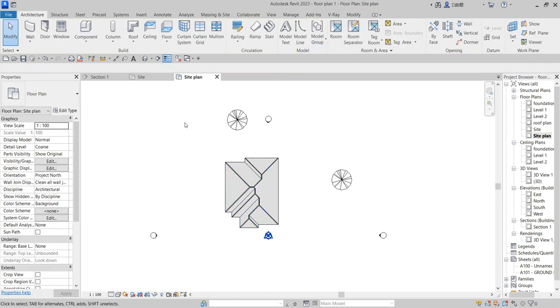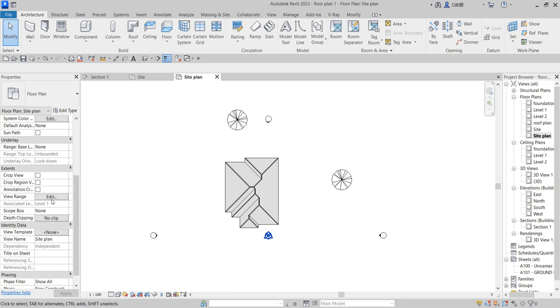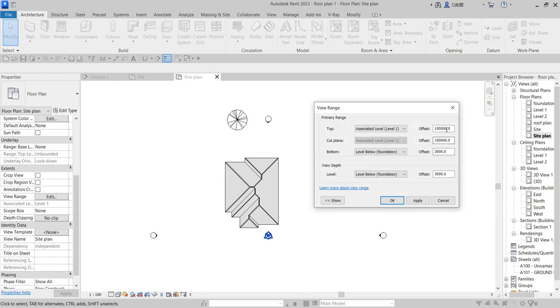So what you need to do is to go to your view, because you want to cut it according to what I'm seeing in the building. Go to your view, click on view range, check view range. Good. You look at this particular level, it is high enough, but you don't want that particular thing to be of such height. So you take it to something like 2100. Now this space again, bring it to 2100 or something lower, like 2000.